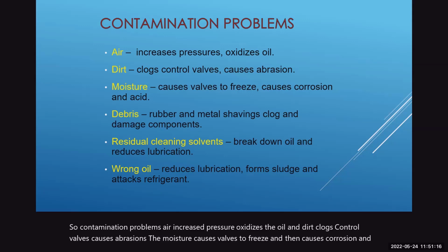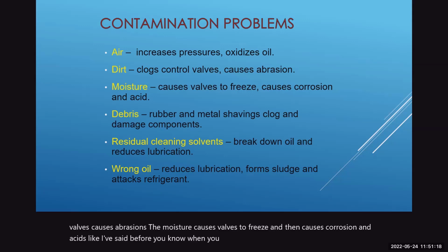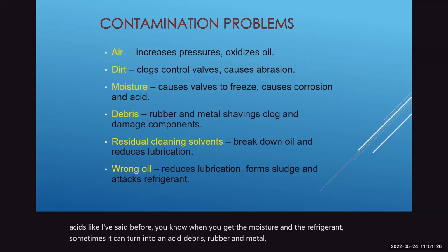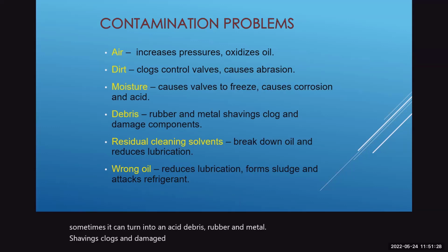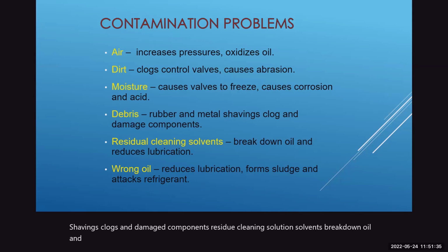Like I've said before, when you get moisture in the refrigerant, sometimes it can turn into an acid. Debris, rubber and metal shavings clog and damage components. Residue cleaning solution solvents break down oil and reduce lubrication. So you have to be very careful what you use to flush the system out.